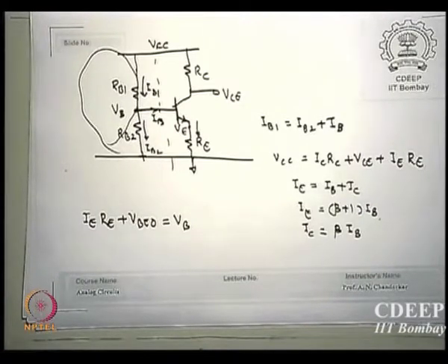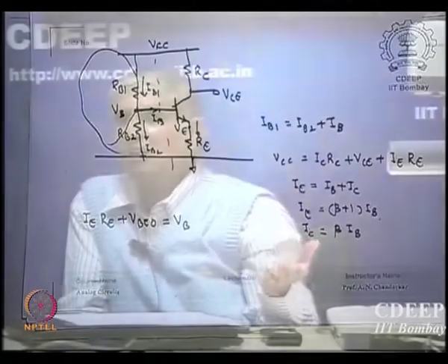This is what you do in the lab. When you go to the lab and you are biasing, you need not worry too much about IB at that time, just choose R1, R2 for a given VB you are looking for, is that correct? It may not be exact, but that is not needed, because 10.001 is irrelevant, as 10 is as much as 10.00. But some things have to be verified. So I gave you some idea: if betas are higher, IB1 is equal to IB2, and just the resistor ratio is good enough for you, is that correct?